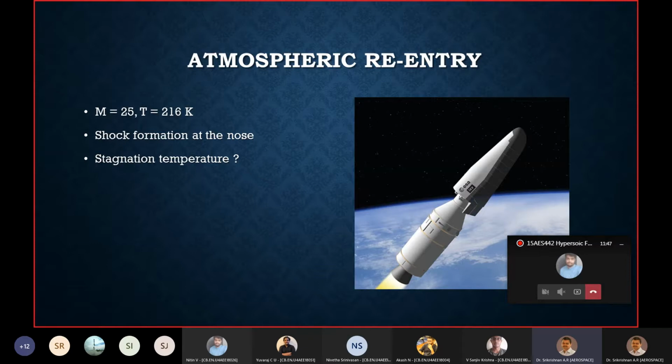But the scramjet concept comes because decelerating hypersonic flow to subsonic will entail huge stagnation pressure loss as well as static temperature rise. Both of these are detrimental for thrust production. Because of the temperature increase, you will have dissociation losses in the combustion, and because of the loss of stagnation pressure, you are going to have thrust loss.